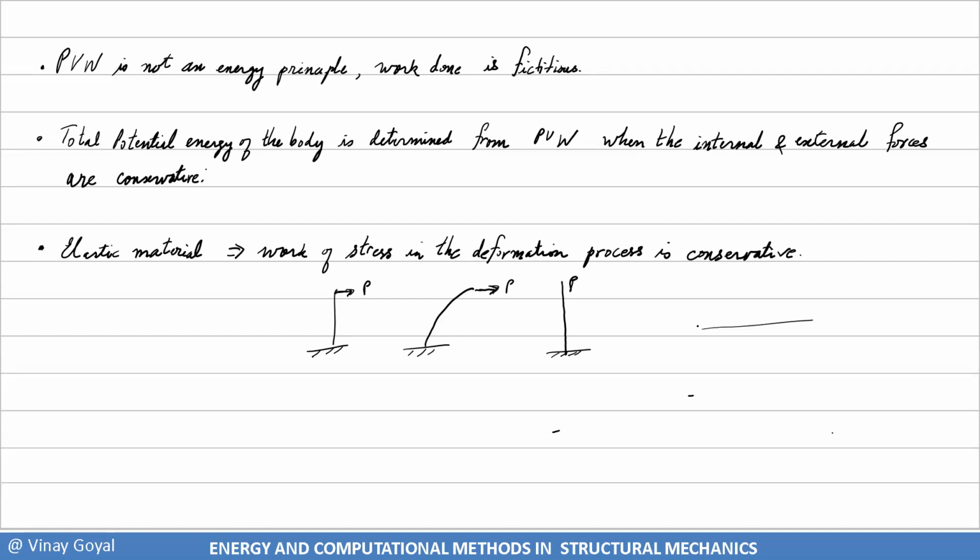But if I apply a load here, and it deflects, and the load changes direction because the beam changed deflection, then this is a non-conservative load.